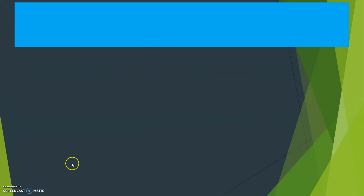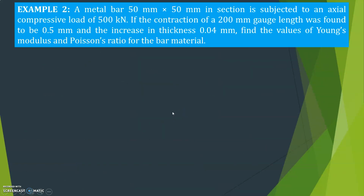A metal bar of 50 mm by 50 mm in section is subjected to an axial compressive load of 100 kilonewton. If the contraction of a 200 mm gauge length was found to be 0.5 mm and the increase in thickness 0.04 mm, find the values of Young's modulus and Poisson's ratio for the bar material.